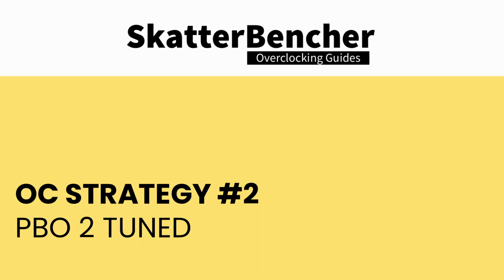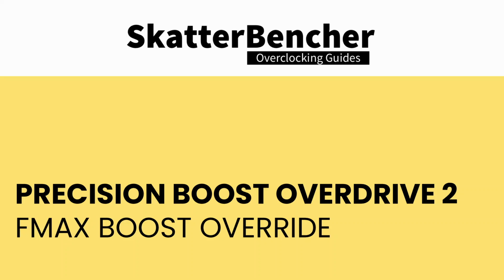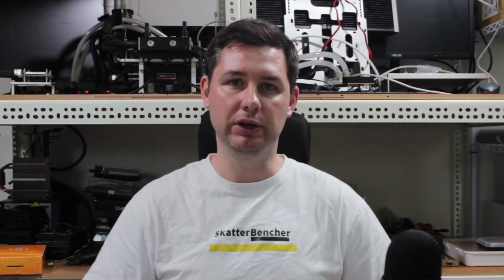In our second overclocking strategy, we tune the parameters governing the Precision Boost algorithm with the tools provided in the Precision Boost Overdrive 2 toolkit. Fused maximum frequency, or Fmax, is one of those Precision Boost limiters governing the CPU performance. Specifically, the Fmax limit defines the maximum allowed frequency for all the cores in your CPU.